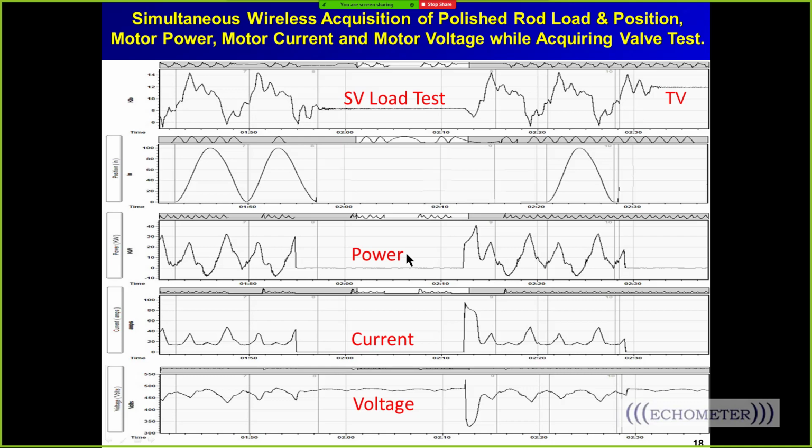And so we can use this current and voltage to calculate the line losses. We can use the current to calculate the thermal loading of the motor, and we can use the kW to calculate the net torque on the gearbox.